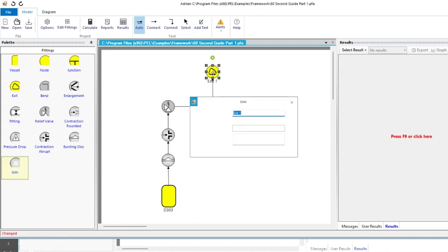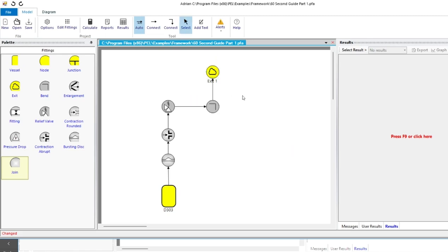One little word on this is that exit. We haven't looked at the exit node yet. Outlet back pressure. So that's 1 atmosphere currently, and that's going to atmosphere. But what this little outlet does is, built into it is that expansion in the pipe. So obviously in the pipe, the fluid is expanding basically to infinity, into the atmosphere. So in modelling terms, infinity means 10 meters. So built in with that exit model is an expansion from your pipe diameter to 10 meters, just to model that expansion and make sure we understand if there's a choke there or not, because that will affect the back pressures going on.